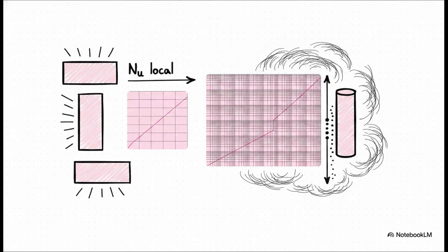This perfectly illustrates exactly how engineers map out convection data. Notice how they use both linear and logarithmic scales, depending entirely on the vast ranges of the data they're handling. For something like local Nusselt numbers on flat plates, a linear scale is often perfectly fine. But the source points out that for certain free convection correlations, like isothermal horizontal cylinders, for example, the data can span 20 orders of magnitude. 20! In cases like that, you absolutely need logarithmic charts to make any sense of it.